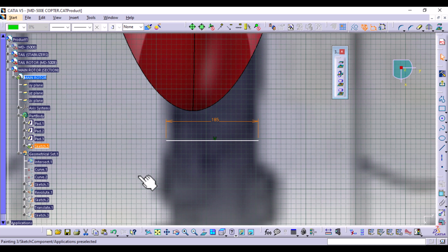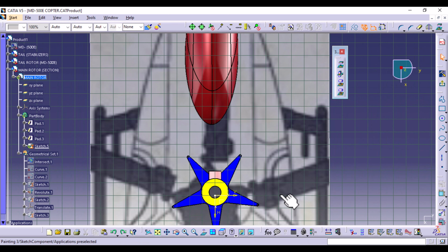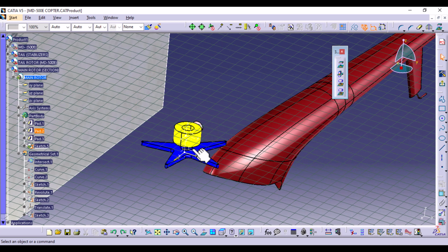And we can go to airfoiltools.com and enter this in the NACA 0012 airfoil plotting section. So undo this. So that's 185. Before we get to the blade, I'm going to create a transition section. So we're going to have a section that is also going to be joining to the blade section, from the circle to an ellipse section here. So I can sketch it here and then translate it, so we don't have to keep creating other sections. So I can sketch this YZ plane.